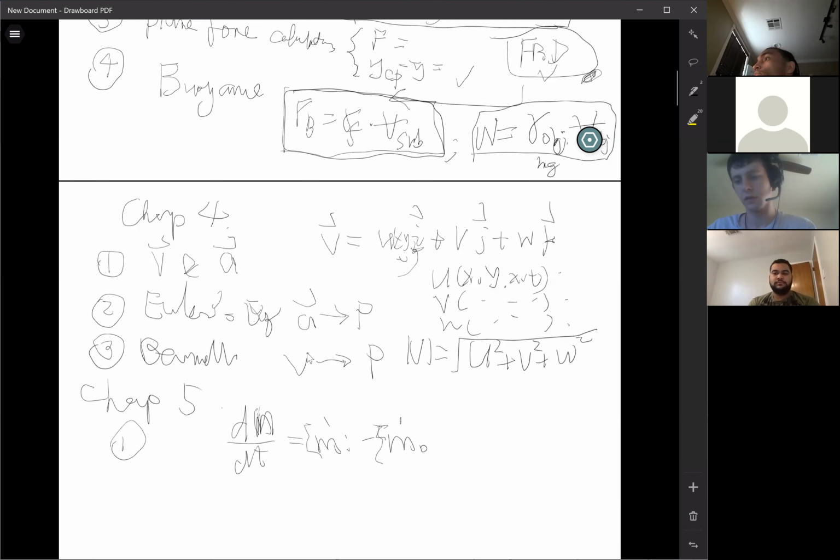That's how we calculate the velocity many times. Remember, if you practiced any of the homework problems in later chapters, conservation of mass is always used, as the flow rate is the same. If it's a steady state, this term is gone, and it becomes mass flow rate in equals mass flow rate out. Density is the same, so basically just Q in equals Q out. We use this to calculate the velocities in the future chapters. In comprehensive problems, sometimes even chapter 4's Bernoulli problems, you need a velocity.